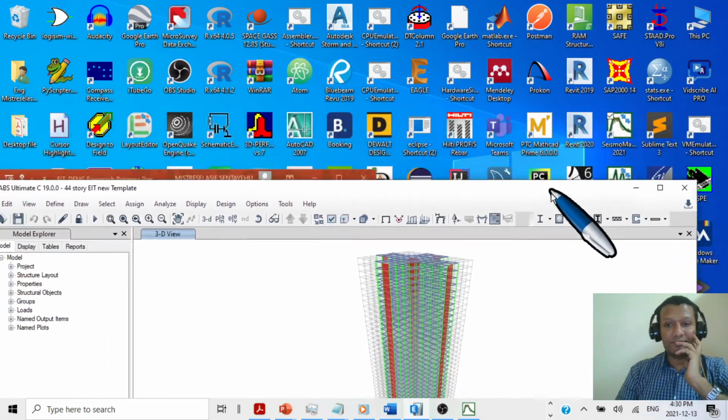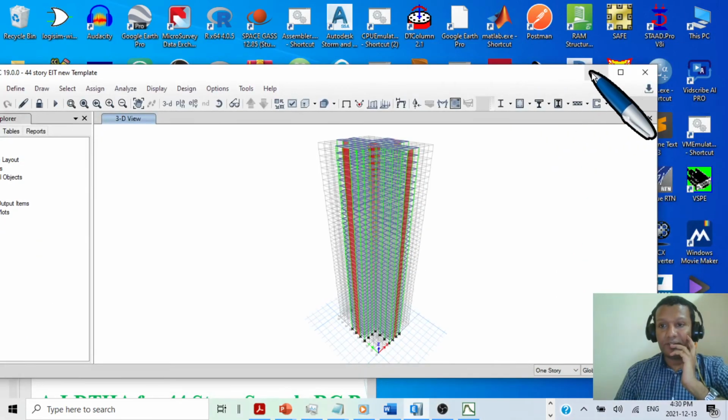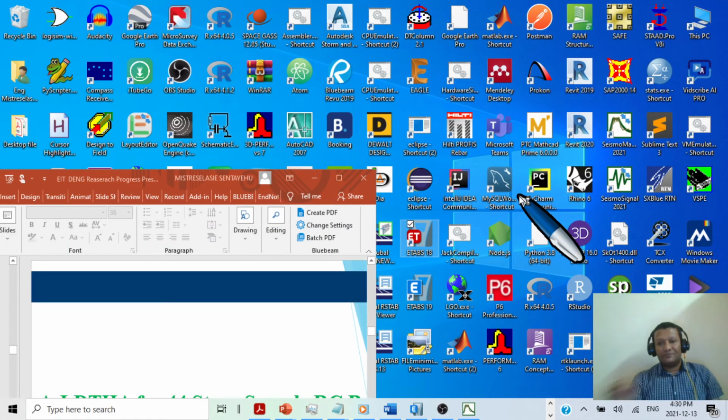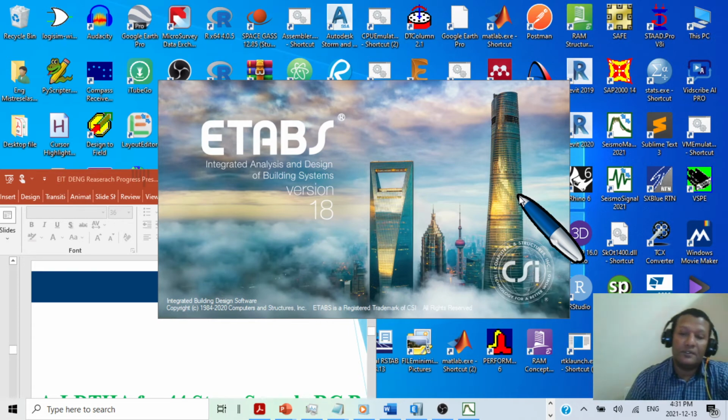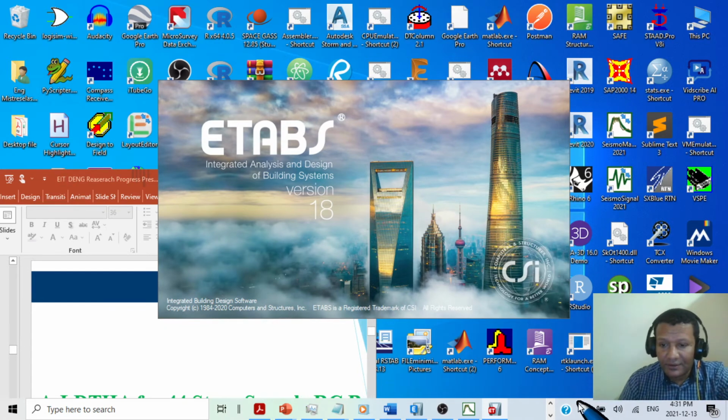Let me open ETABS just for demonstration, because we have two methods, SeismoMatch, and ETABS also has a capability to match the response spectrum directly, but we cannot take out the matched data from ETABS, whereas in SeismoMatch, as I showed you, you can directly extract.